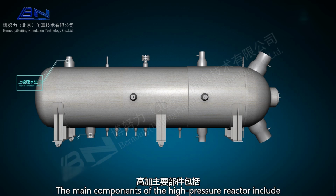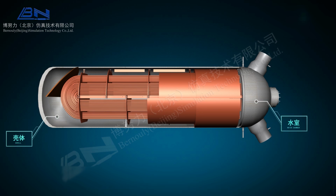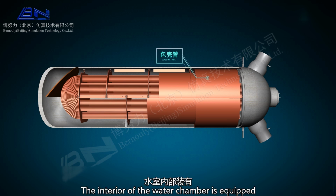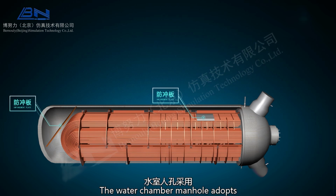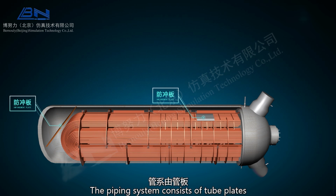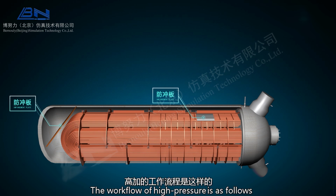The main components of the high-pressure heater include composite water heat exchange tubes, supporting plate, cladding tube, and anti-collision board. The water chamber is a hemispherical one. The interior of the water chamber is equipped with a partition. The water chamber manhole adopts a high-pressure manhole self-sealing structure. The piping system consists of two plates, U-shaped pipe, partitions and other components.